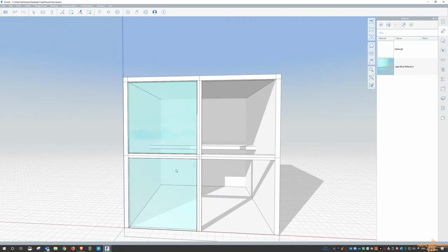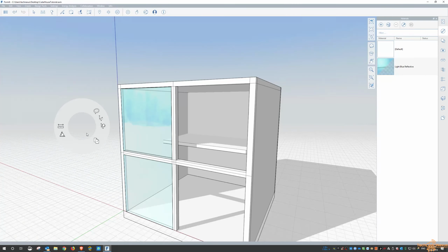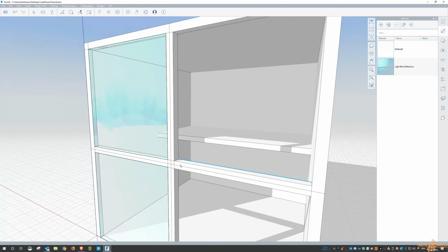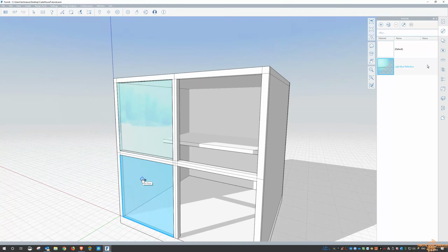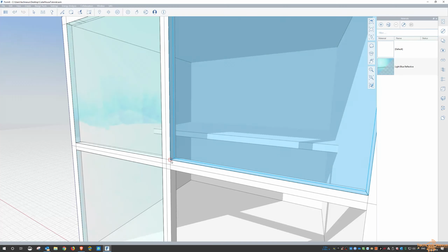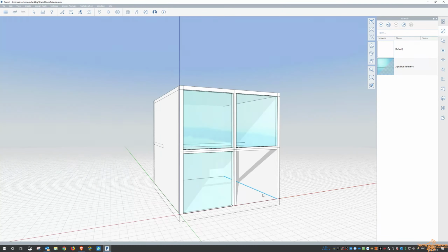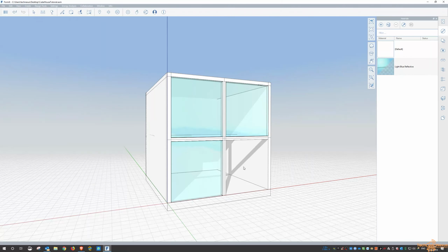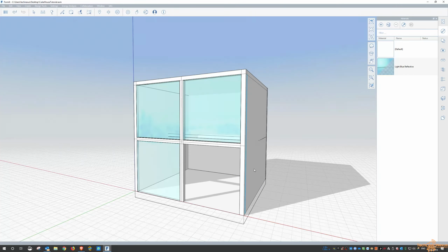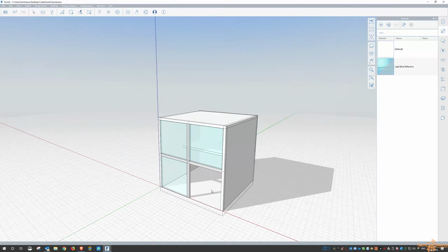Oh, so we've got two windows in there now, and we right click, paste, oops, wrong one, right click and copy, and then right click and paste, and then do the same for here. Okay, and then what we might do here is maybe put in some doors later as a family, and then sort of draw up some more window frames, but for now I'm just going to leave that as is.